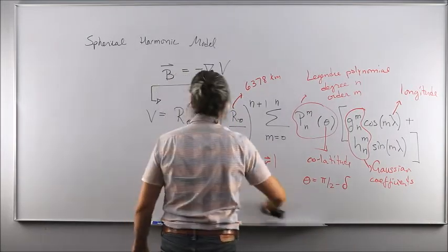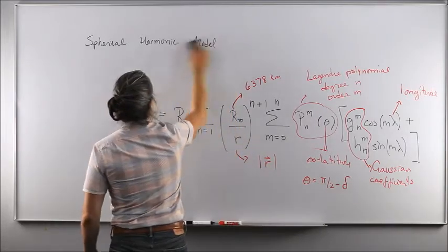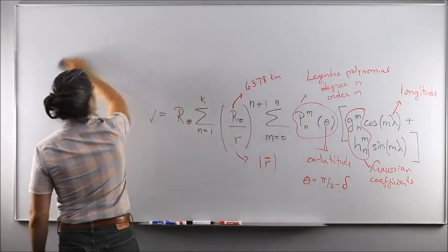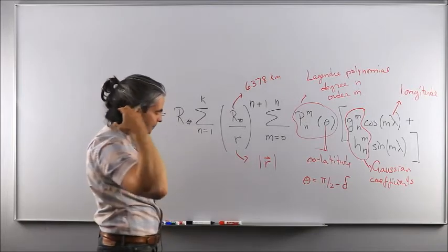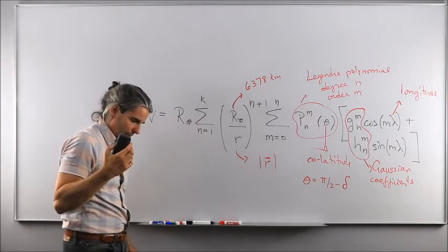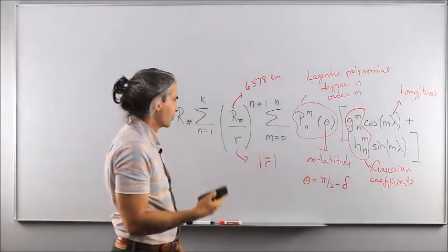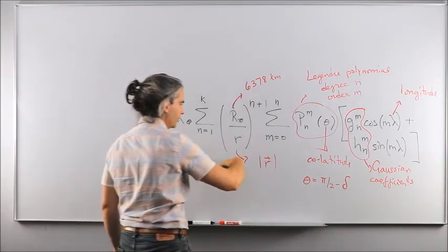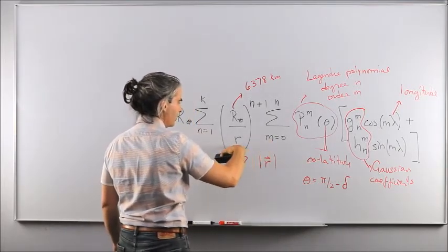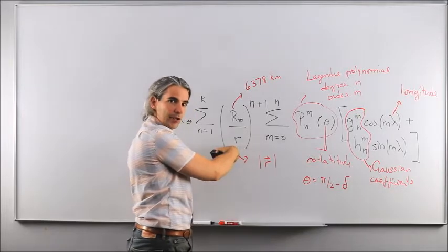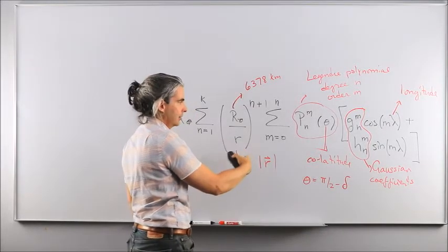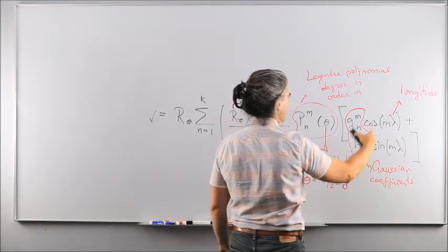Nice. Well, nice and not too nice, because it means that in order to ultimately obtain the magnetic torque affecting the spacecraft, we need to simulate the orbital motion, because we need to know r, the position between m1 and the spacecraft instantaneously, as well as the latitude and longitude.